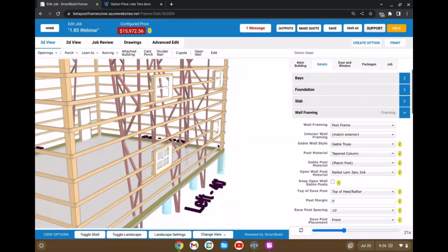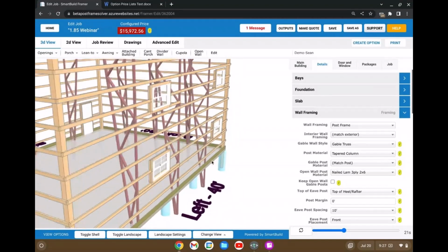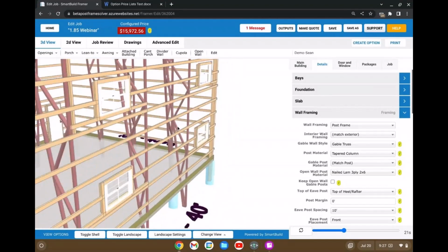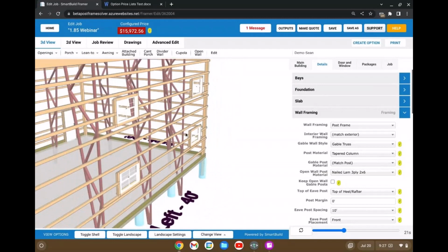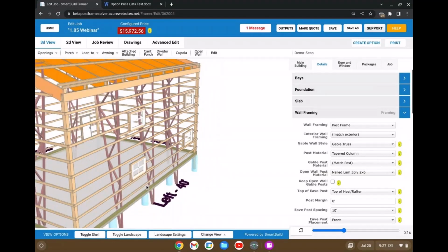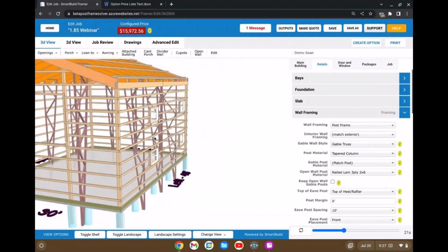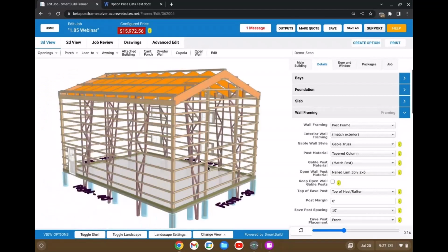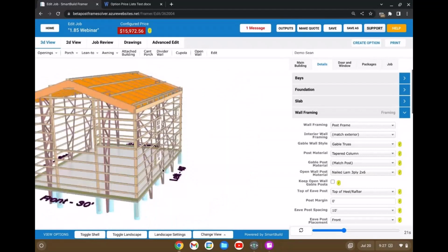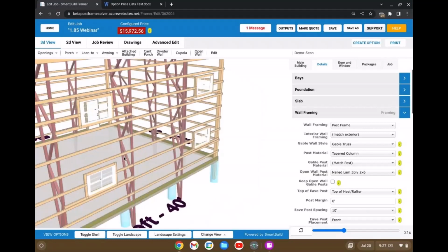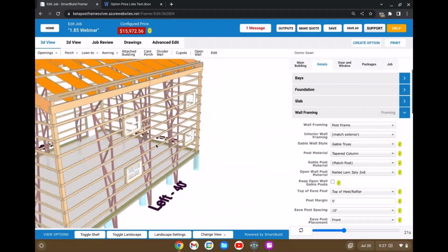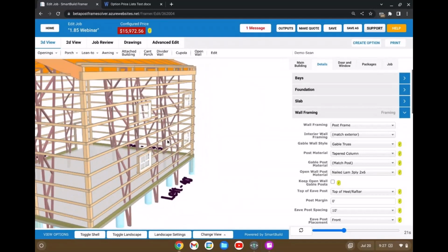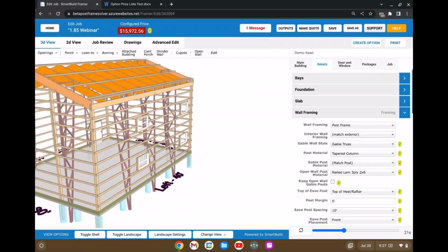I'm not going to get into it too much, but just so you see what this looks like, it's using that bar joist shape, and it's tapering from 6 inches up to 24 inches here. So it's just a generic linear taper. But if you do want to get that kind of look, and usually it's going to be like a steel member, you can have this come in as like an LVL or something if that's something you would do, but I just have this set up with the web header. So that's what that looks like.